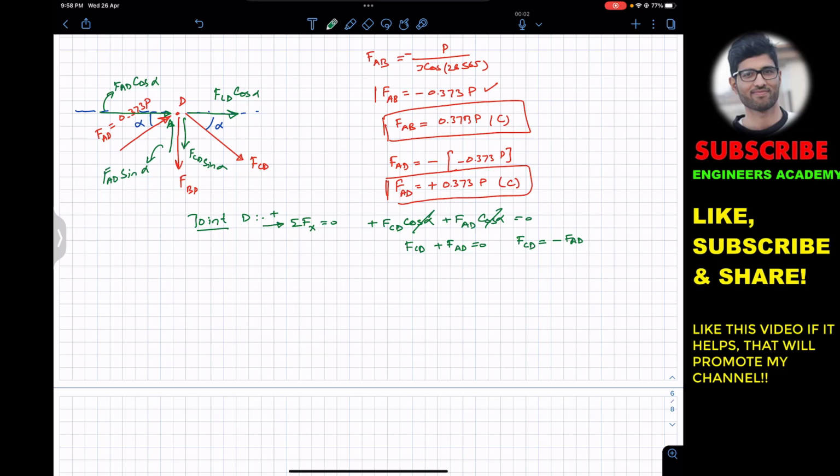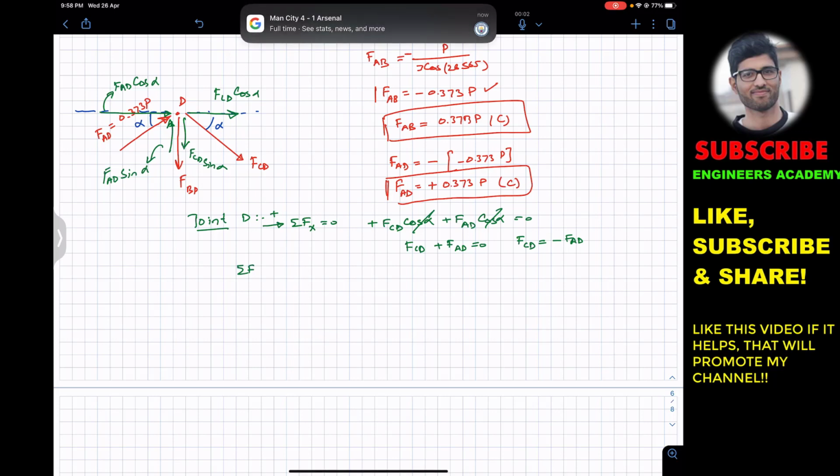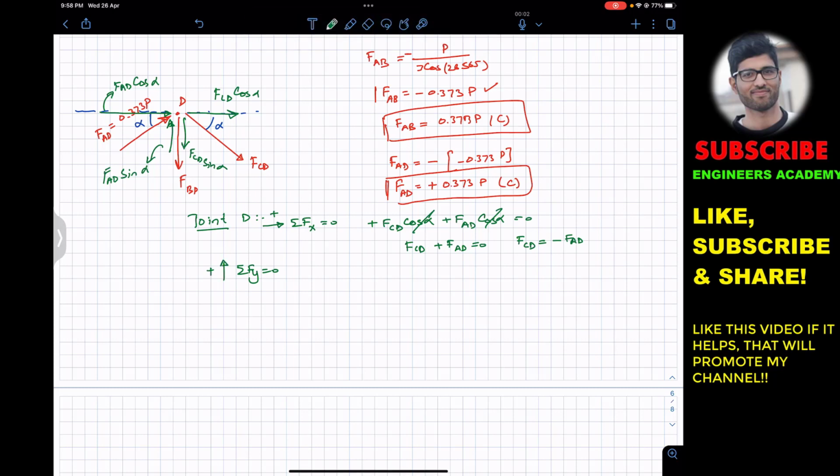And similarly, if I apply the summation of forces along y equals to 0, and this is our positive y direction, now we have FAD sine of alpha, so plus FAD, and FAD magnitude is known, which is 0.373 P sine of alpha.